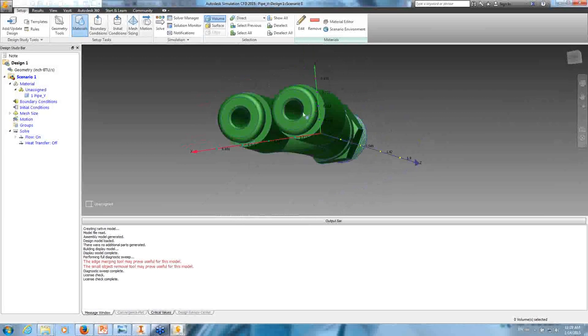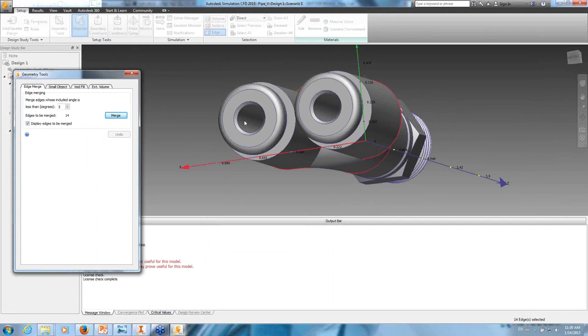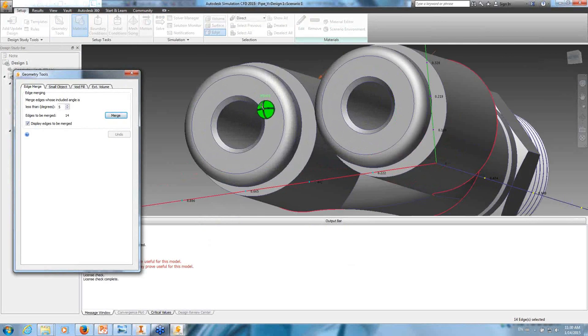So how do we generate the fluid inside of it if we didn't do that already in our CAD model, which most people don't? To do that, I will go to the geometry tools. And basically what I need to do is I need to plug these 3 holes, create surfaces to plug these holes, and then I can generate the volume inside once it's watertight. That's going to be quite easy here.